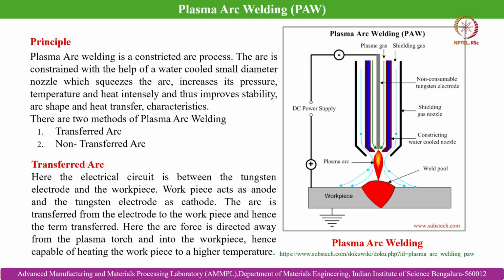It is a constricted arc process. The arc is constrained with the help of a water cooled small diameter nozzle, which squeezes the arc and increases its pressure, temperature and heat intensely, and thus improves stability, arc shape and heat transfer characteristics.